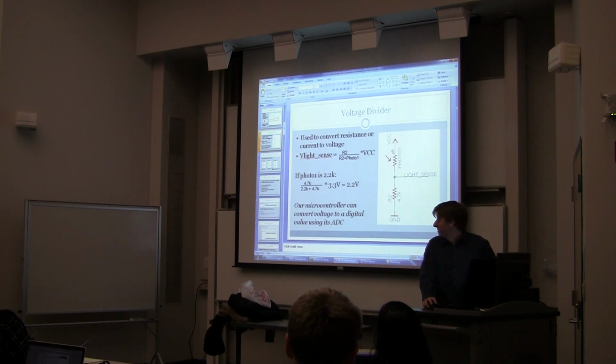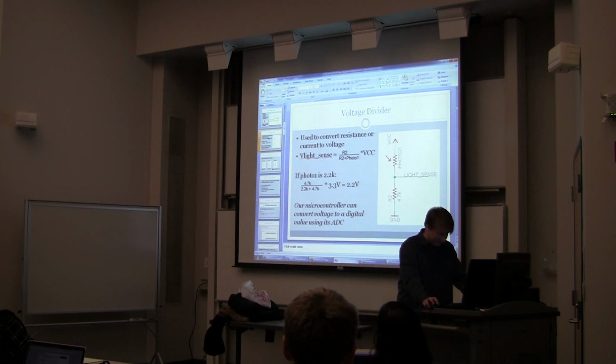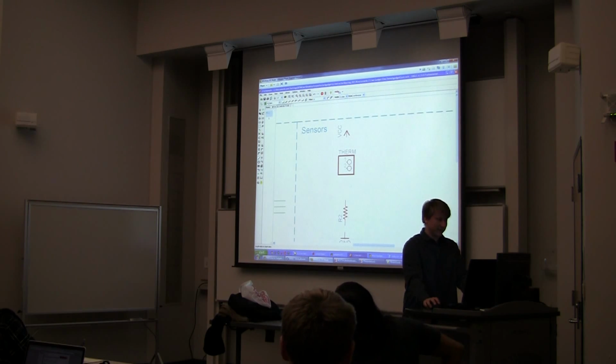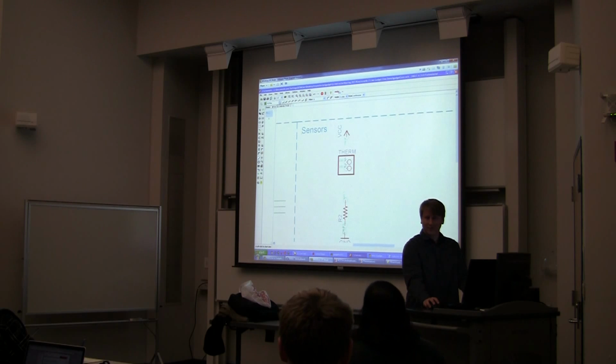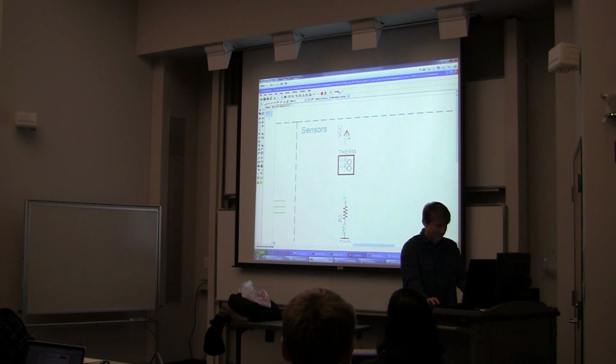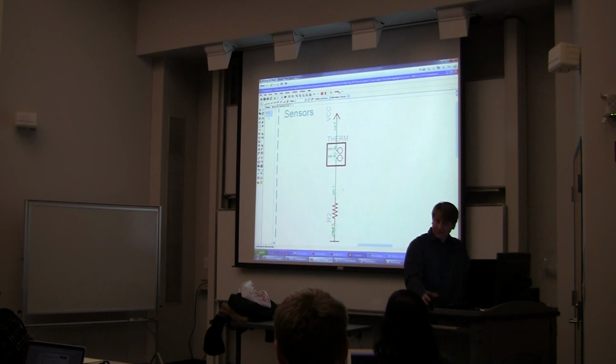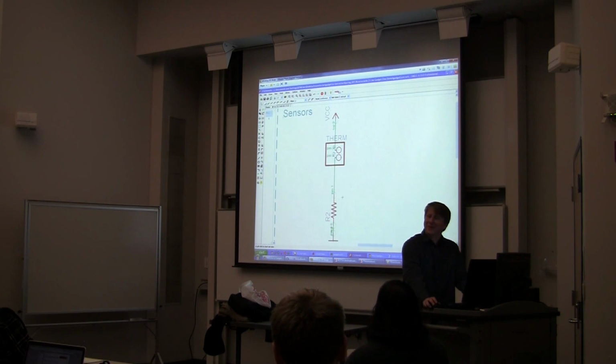And now if you remember, we got to make those nets to connect everything. So I'm going to use the net command. You can also use the wire command, but then you might forget and be on the wrong net layer. So I always use net. So then we just go here, connect it. If my sound was on, it would make a happy ding sound, I think. Okay, so now I've made some nets. Yep. When you get those little circles to show up, it shows you exactly where to wire to on the component.